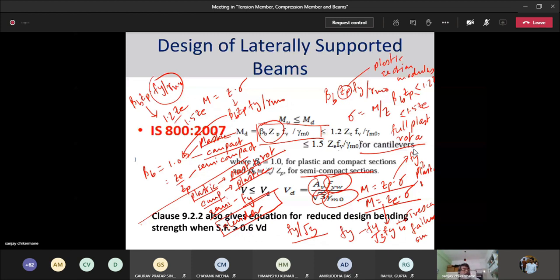I'm not going to get into different kinds of failure surfaces because you've got von Mises, Tresca, Coulomb, Drucker, all of which are different types of failure surfaces. We just say that this is what your failure surface is, if it is an octagon in some sense. So your fundamental concept is that your Mohr-Coulomb failure surface is an octagon.